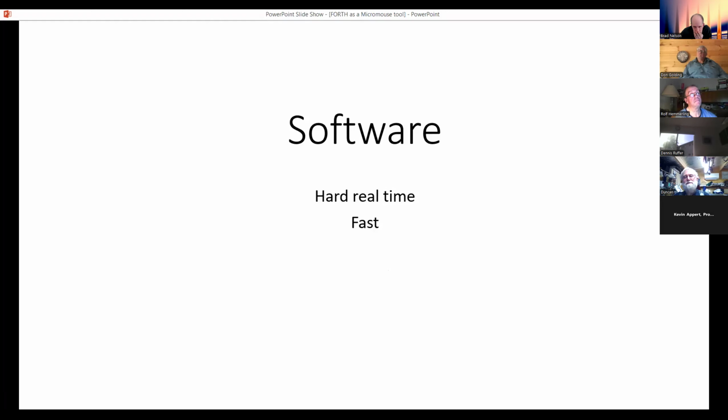Now we come to the stuff that you're probably most interested in, software. So software brings it all together and can help to solve problems caused by failings in other bits. It's proper, hard, real time. As I said, any variation in the sampling times for the sensors or the odometry comes out directly as noise in the control loops. So it will affect how accurately you can control the robot.